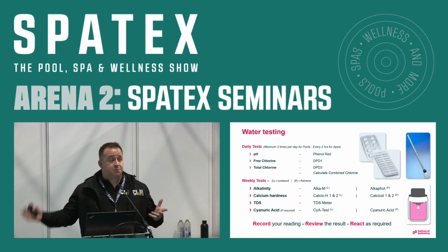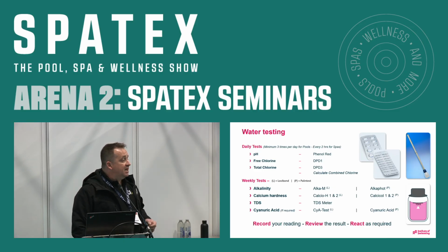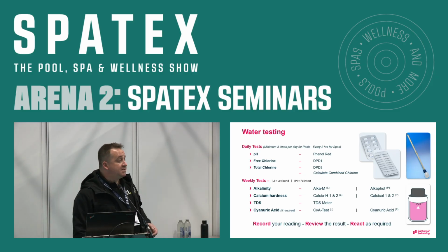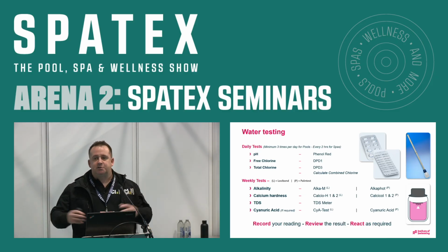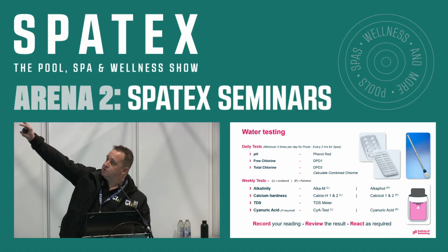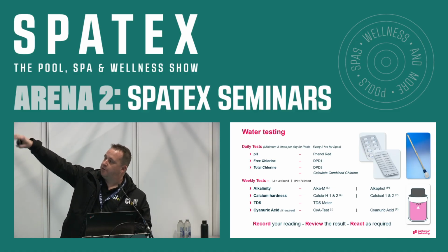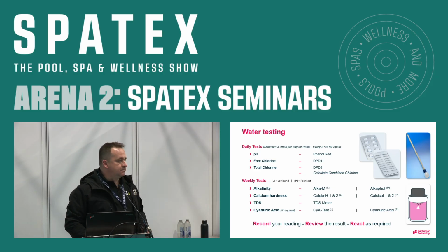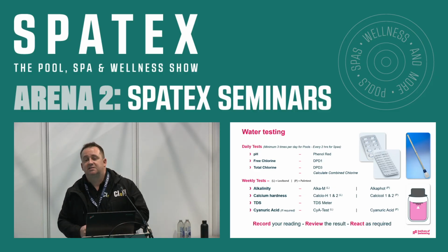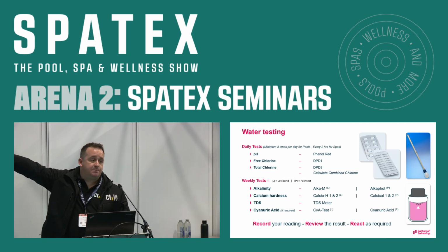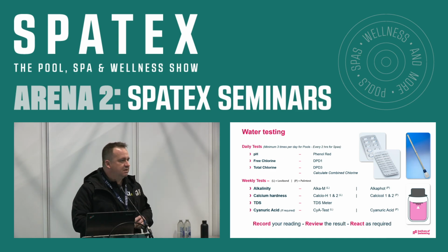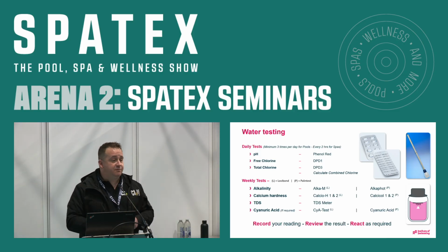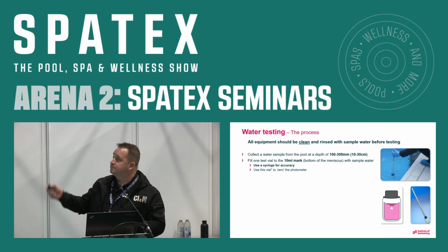There are other tests we can add too. PWTAG recommends that if we're using certain chemicals, we might want to do sulfate tests, phosphate tests, maybe even copper tests, depending where we are in the country. That is individual to you at your site. But the top daily tests are pH, free chlorine, total chlorine. Weekly tests are alkalinity, calcium, TDS. Record your readings, always. A single water test, when we look at balanced water testing, is next to useless. Three months' worth is a usable body of information.